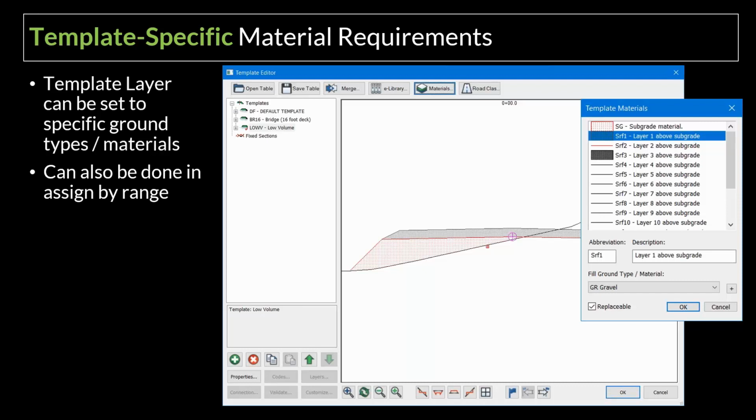By default, we don't. But if we want to account for, say, your surfacing material or other materials for different uses, could be armoring, etc., we can say I want surface volume 1 to be associated with bill material X. And if we want it to just be X, not replaceable based off of the quality of X, we'll uncheck that replaceable box.